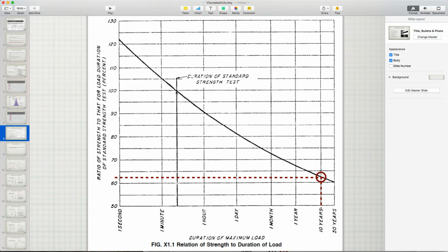So what the Madison curve says is, I got this piece of wood. Let's say I'm using additive manufacturing, and I am printing 2 identical pieces of wood or pseudo wood things. Yeah, we could do this now with additive manufacturing, kind of surrogate stuff. All right, I got 2 identical pieces. I take the first one, I test it, and it breaks at 8,000 pounds in 10 minutes. We'll call that our baseline, or 100%.